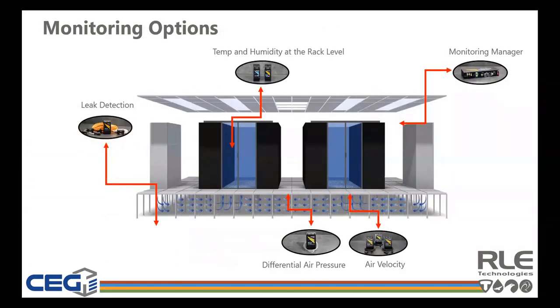Thank you, Tim. So this brings us to our last best practice, monitoring. An effective way to know if you're providing enough cooling for a given rack or row is to monitor temperatures. Temperature monitoring ensures that low airflow areas, and therefore typically higher temperatures, are identified and can be addressed.